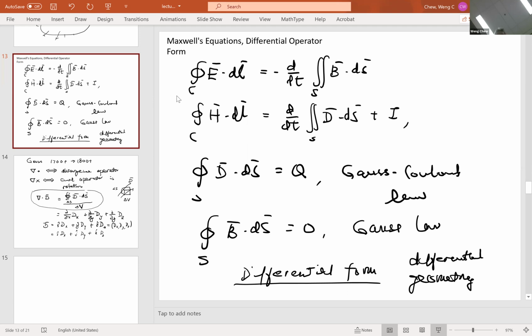That voltage, if I compute according to the left-hand side, will give me a voltage on this current loop, and that is proportional to the flux linkage B, or dB/dt. The time variation of the flux linkage through that loop gives me the voltage. That is essentially Faraday's law.